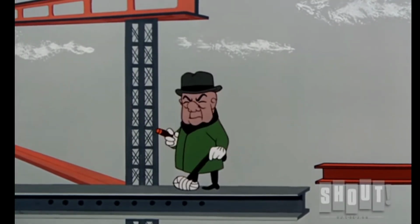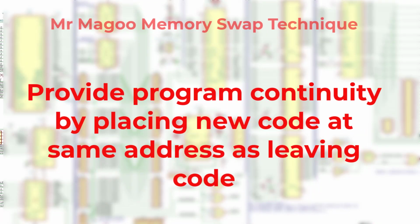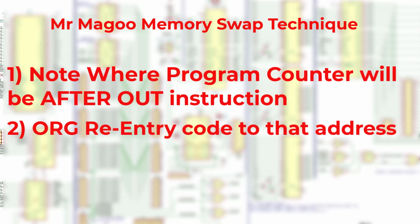So this means that to use the Mr. Magoo technique, we need to make sure that whatever memory device is being swapped in has the program continue from the existing address from the memory device being swapped out. And in the simplest case, you can just take the address out of the program counter following the out and use that address to org the location in the other memory device with an instruction, maybe something like a PCHL.